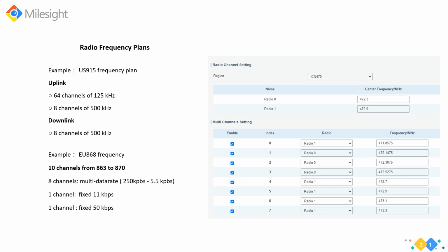In the same region or the same country, or surrounding your solutions, maybe there are other LoRa solutions being operated or under way. So other customers may probably set up their radios with the same frequencies as yours. In this situation, your preferred frequencies may be used by someone else, which would cause signal interference and increase the packet loss.